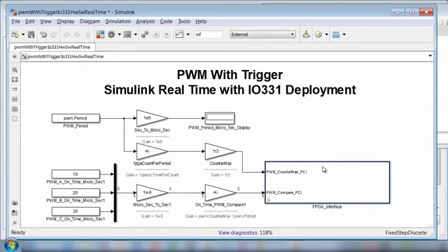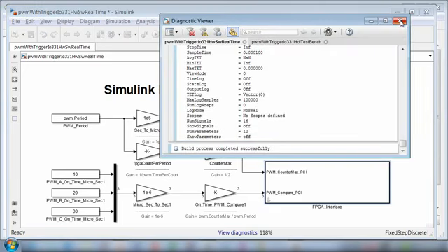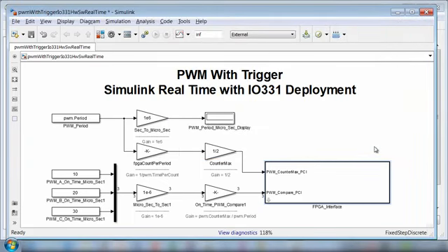One of those things is it specifies the FPGA programming file, which we call a bitstream file. So as part of this build process that I've initiated, not only will C code be generated to program the CPU, but the appropriate FPGA bitstream file will be automatically downloaded and used to program the FPGA, and that happens for me automatically. So just a quick check to see if that's complete. It is. Okay, so now I have built and downloaded the application. It's ready for me to interact with it on the hardware.